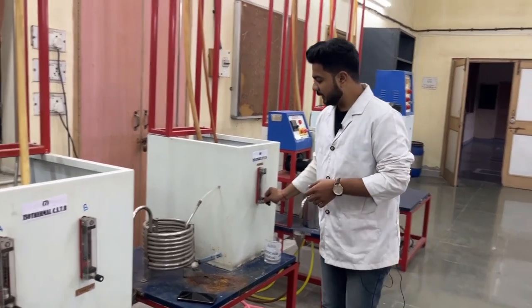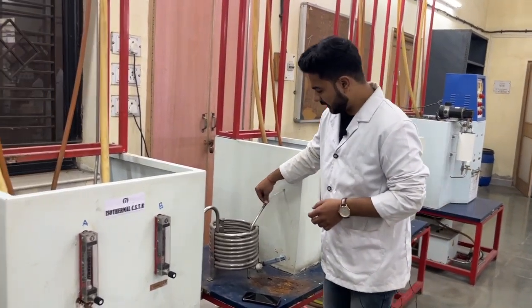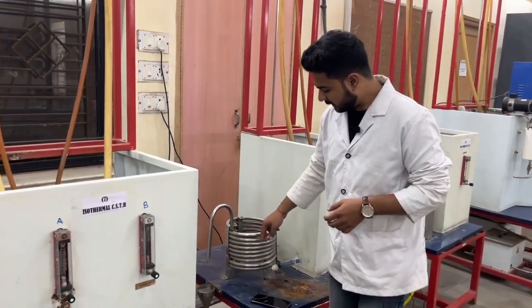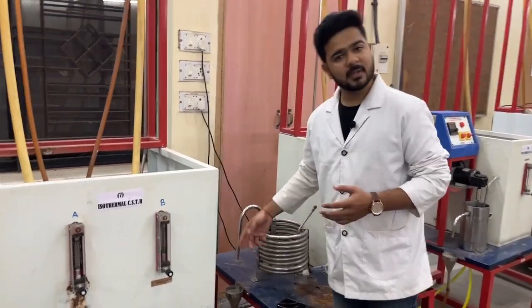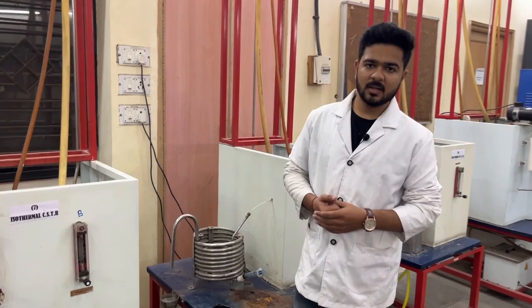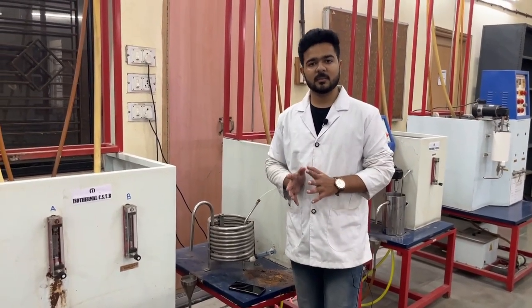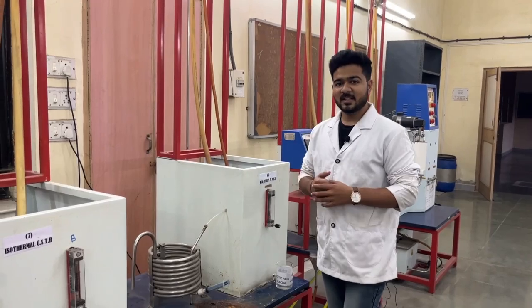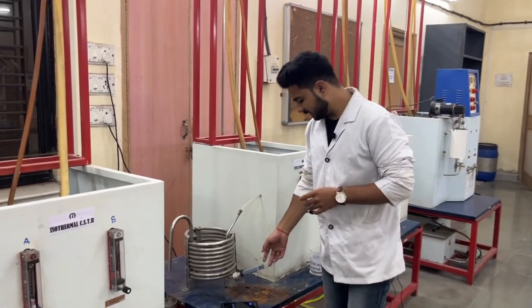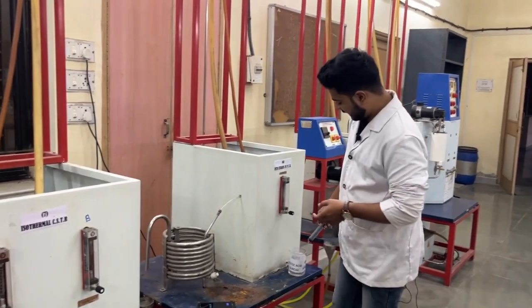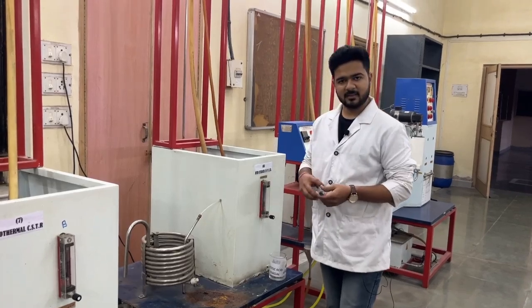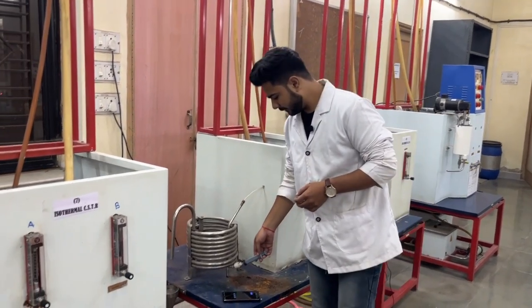We will notice that liquid has started flowing in the reactor. When the liquid comes out from the outlet, we will again wait for the steady state to be attained. For this flow rate, we will wait approximately 6 minutes. Now we will again set up the tracer input for the second reading. We will take 10 ml of acetic acid as a tracer and put it in the tracer inlet.